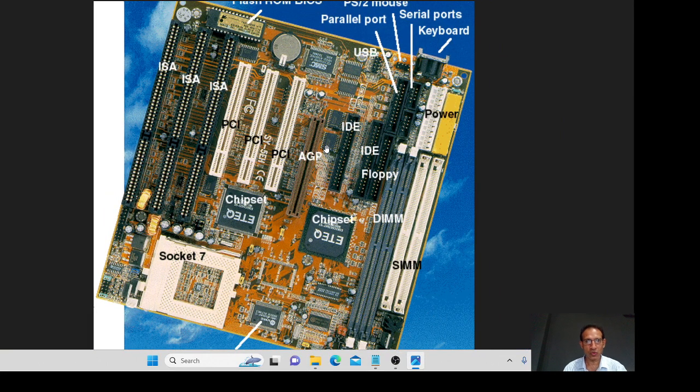If you want to get the display, that particular card should be plugged onto this AGP. ISA and PCI can also be used for VGA graphic cards, but AGP is faster than ISA and PCI graphic cards or VGAs.